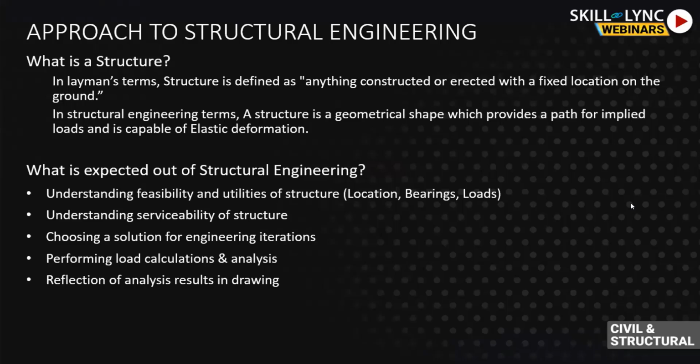And accordingly, one has to understand the loads that would act, and ideas for loads that one might get from Indian standards, that is IS 875 Part 1 through 5. Next, on a structural engineer's expectation comes understanding the serviceability of the structure. We did understand what utilities or what sort of requirement a structure needs to fulfill, but for how long is also a main criterion for any structure. And the code suggests 25 years, 50 years of serviceability, and accordingly, there are important factors that need to be accounted for in engineering solutions.